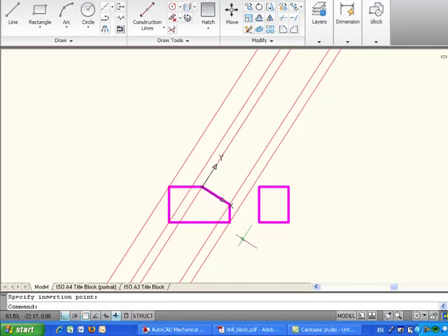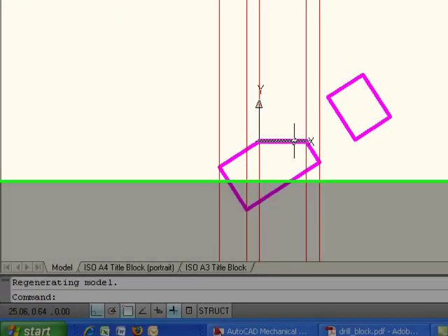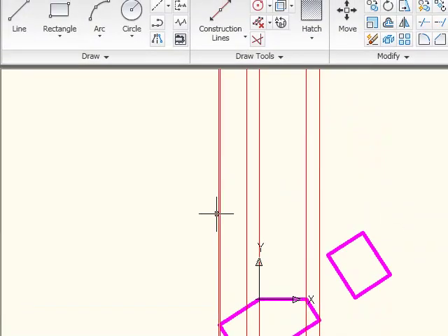Okay, we've used the UCS command to line up the views. The next command I'm going to use is one called plan, P-L-A-N. Just type in P-L-A-N and enter. And it asks, do you want to align with the current UCS? Yes, we do. And if you look at it now, what it does is it makes that XY plane appear in the XY direction, which is useful when you're drawing this next part.